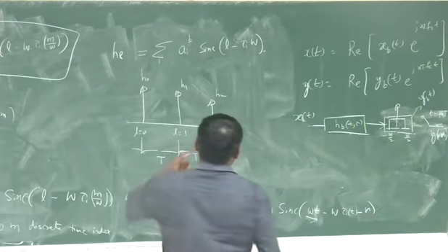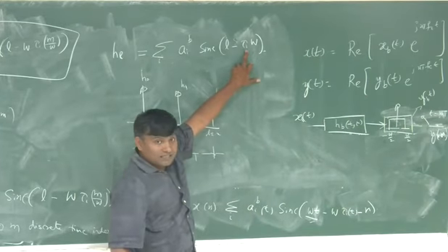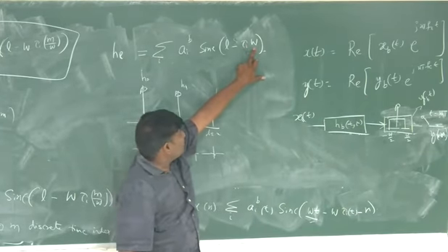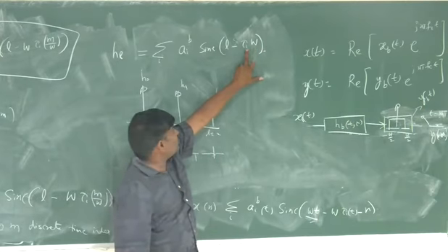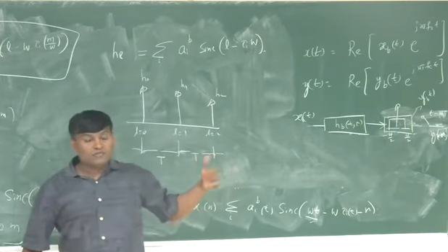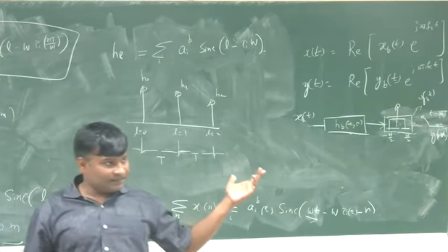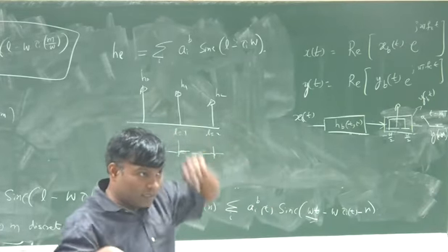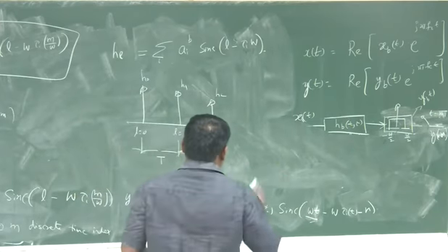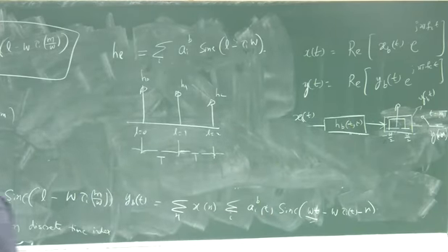Well, narrow band and wide band is decided by W, how large or small W is with respect to tau_i. In this case, we should take tau_i max. Right? The delay spread is there. We should take the tau_i max. Let us say the original channel. Let's look at a hypothetical case here. The original channel.